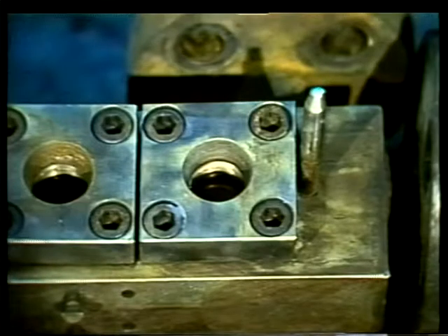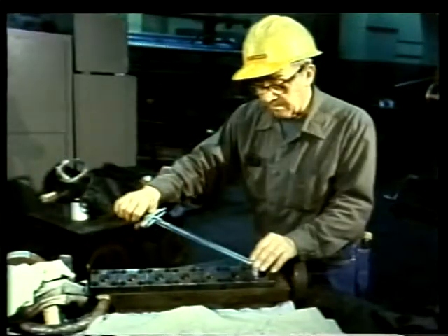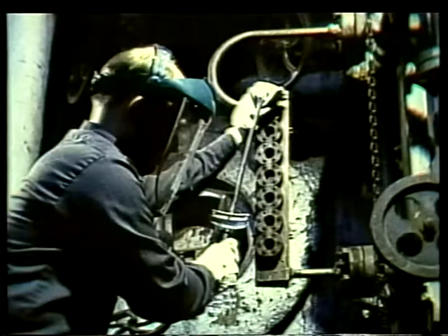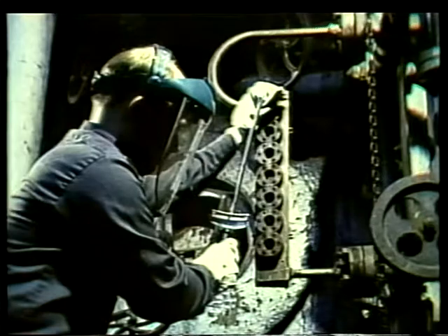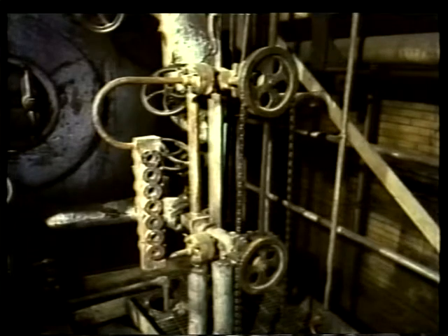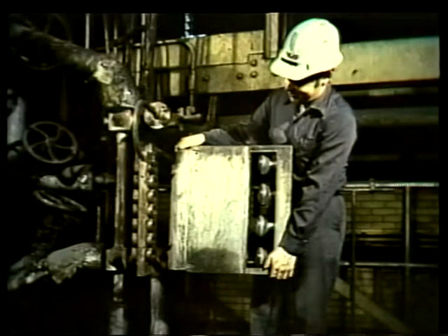Put the cover plate assembly in the gauge and replace the cap screws. Torque the cap screws according to the manufacturer's instructions. Heat up the gauge and retighten the cap screws. Then return the gauge to service and check for leaks. Finally, reinstall the illuminator.